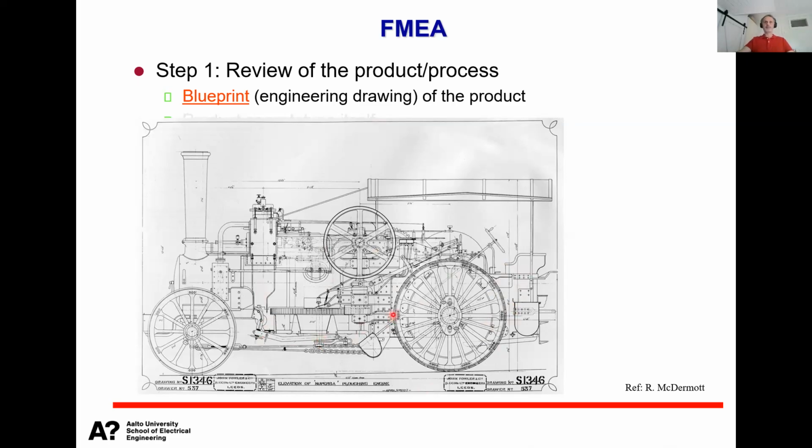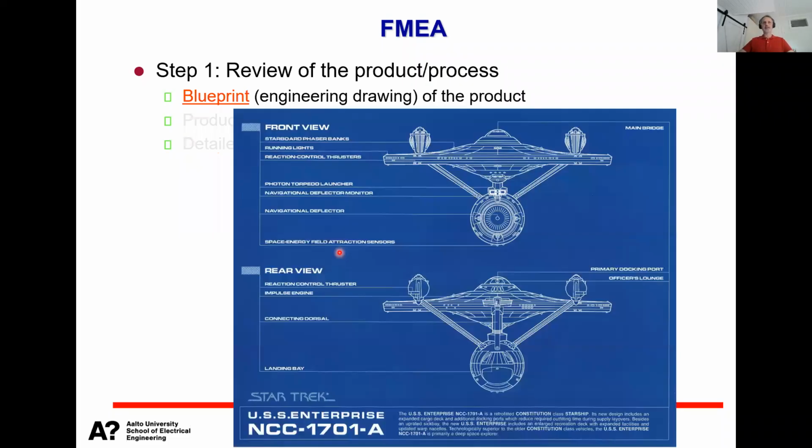So again, tearing the product into parts and thinking for every part what can fail, how these can fail, and what is the consequence. So now in FMEA, the consequence is kind of the key thing, and that is the RPN. One out of 3 parts of that is the consequence, the severity of the problem. So if this was an ancient example, maybe this is a future example.